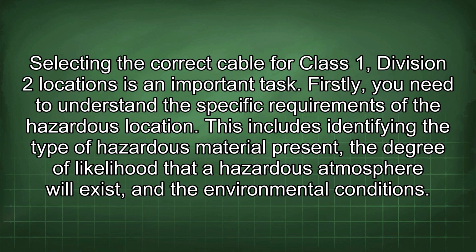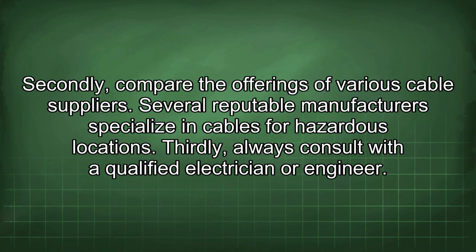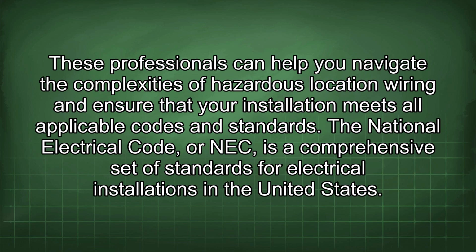This includes identifying the type of hazardous material present, the degree of likelihood that a hazardous atmosphere will exist, and the environmental conditions. Secondly, compare the offerings of various cable suppliers. Several reputable manufacturers specialize in cables for hazardous locations. Thirdly, always consult with a qualified electrician or engineer. These professionals can help you navigate the complexities of hazardous location wiring and ensure that your installation meets all applicable codes and standards.